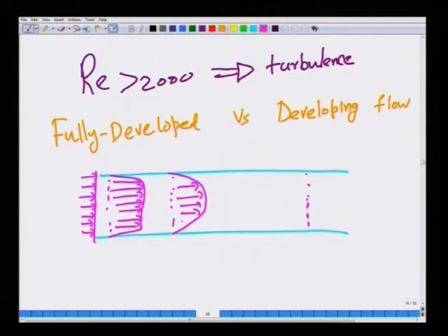Momentum diffuses from regions of high shear rate to lower shear rate. Okay. High shear stress, low shear stress. So, shear stresses are higher here. So, momentum diffuses in these two directions, and it tends to, okay, finally diffuse through the entire region of the pipe, okay, and you will get a parabolic velocity sufficiently downstream.